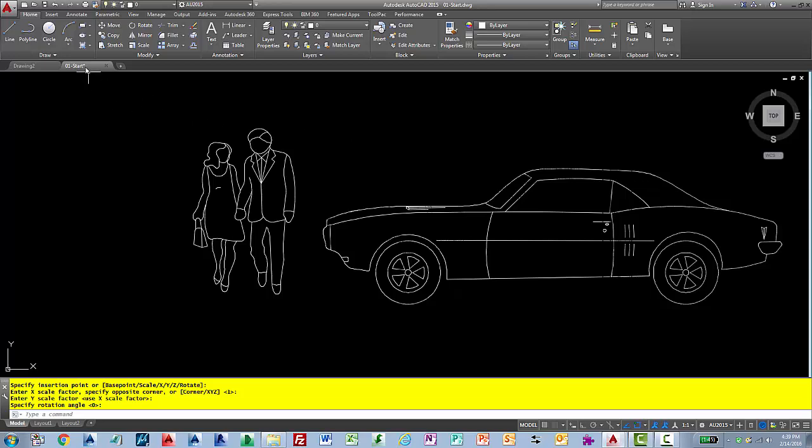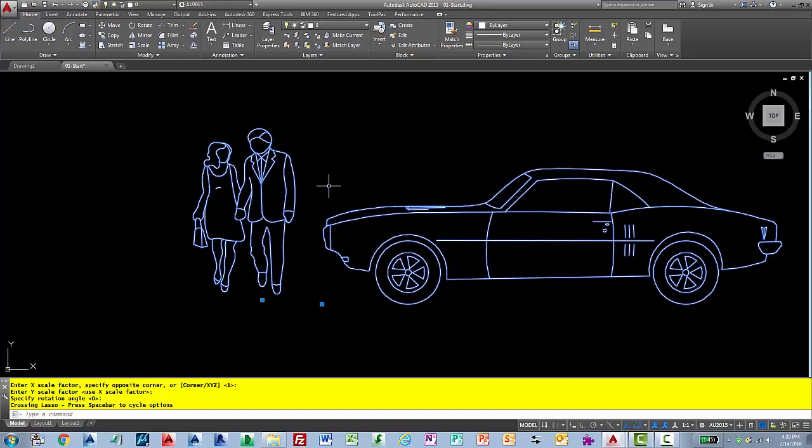And remember, if you drop onto any of the tabs or the application menu, AutoCAD is going to open up that drawing. And if you drop into the command line area in here, it's actually going to insert those as blocks.